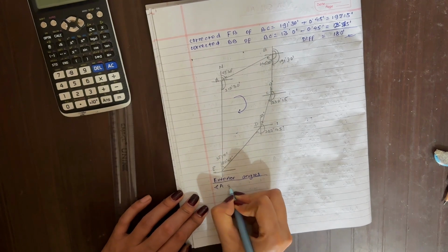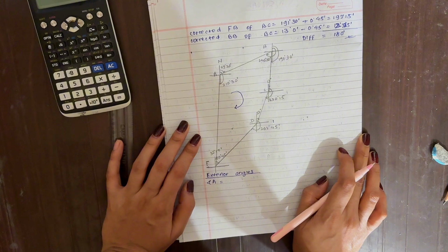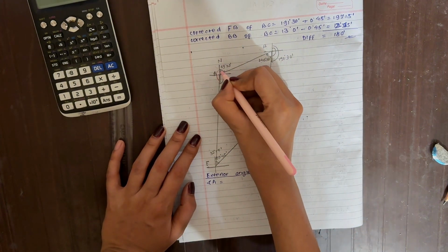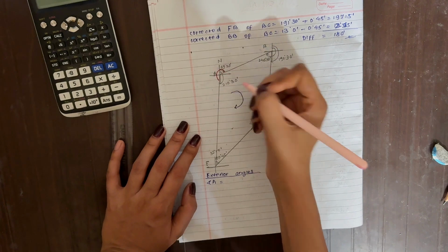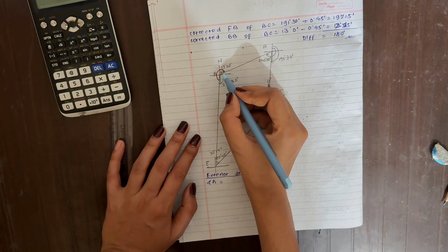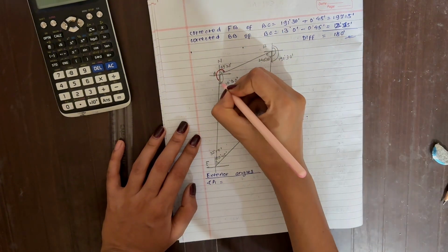So angle A is equal to, so this is just a simple mathematical calculation that we have studied in geometry in school. Here for angle A, the exterior angle must be this remaining. If we subtract 69 degree 30 minutes from this total 210 degree 30 minutes, then we will get the remaining angle up to here.